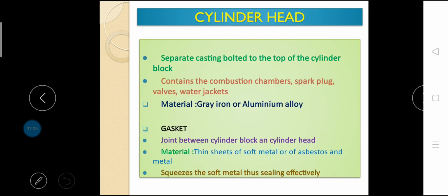Let's discuss the cylinder head. It is attached to the top surface of the cylinder block, called the block deck, by means of studs fixed to the block. The gaskets are used to provide a tight leak-proof joint at the interface of the head and the block. The cylinder head forms a combustion chamber above each cylinder. It also contains valve guides, valve seats, ports, coolant jackets and threaded holes for spark plugs or injectors. Besides, there are other threaded holes for attaching various components and a number of unthreaded holes for attaching the head to the block. There are also some machined surfaces for leak-proof joints. On overhead camshaft engines, provisions for mounting the camshaft and related parts also exist.